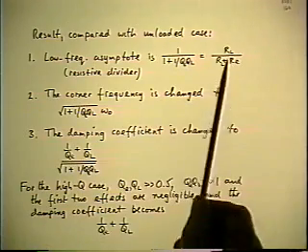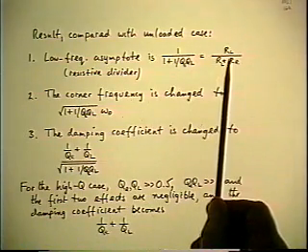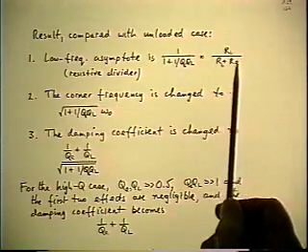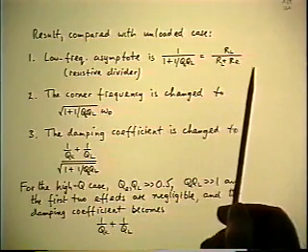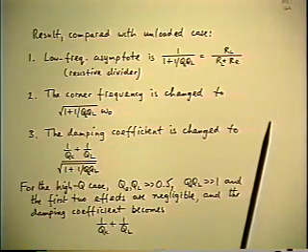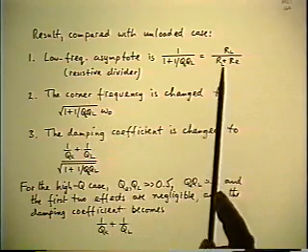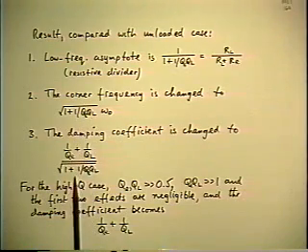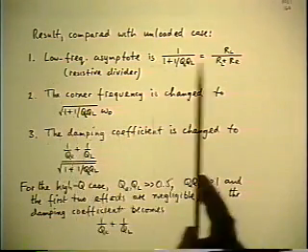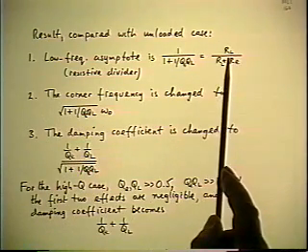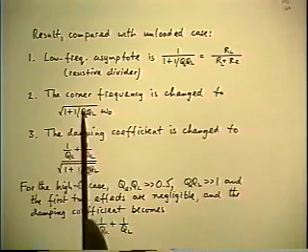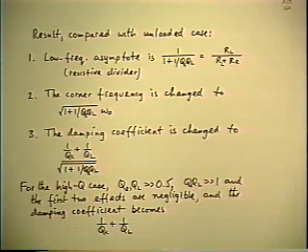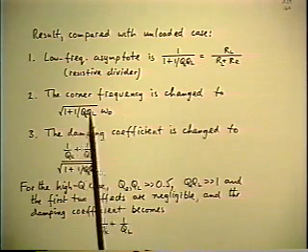So to maximize the efficiency, you're certainly going to design the filter so that this ratio is as close to 1 as you can make it, which for a given load, of course, means you have to minimize the RE, which is the parasitic losses. Now, that's a useful piece of information, because you notice this same factor shows up in these other two effects. So if it is necessary that the filter have this ratio close to 1, it follows that these other two effects can be simplified. In other words, there will be a negligible change of corner frequency, because it's the same factor.